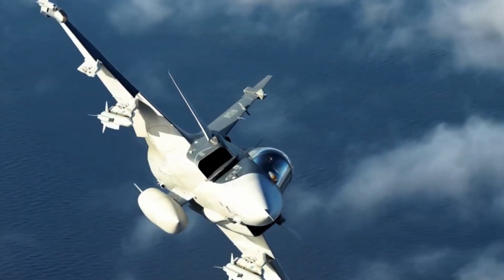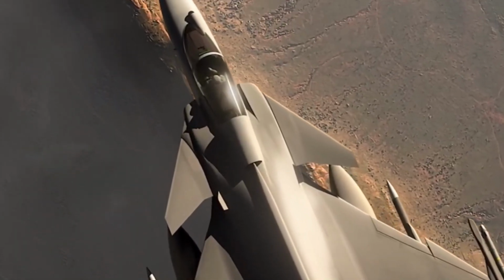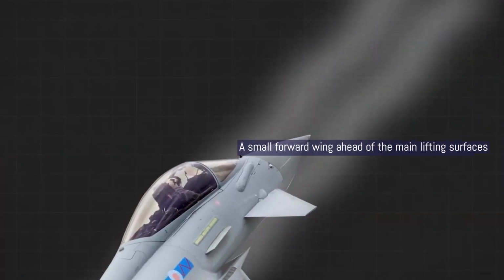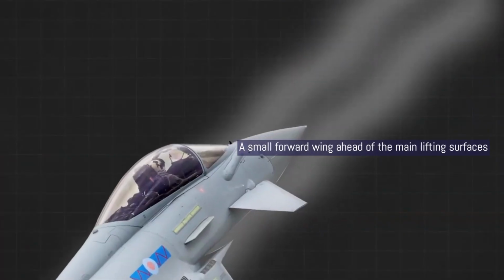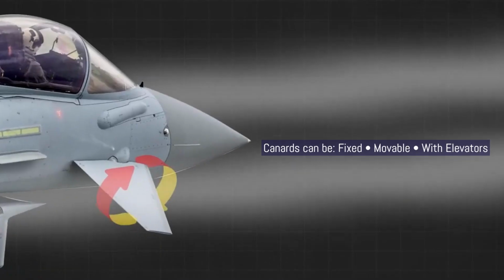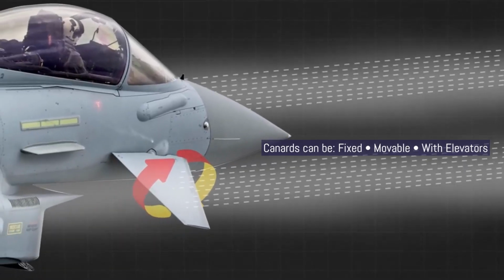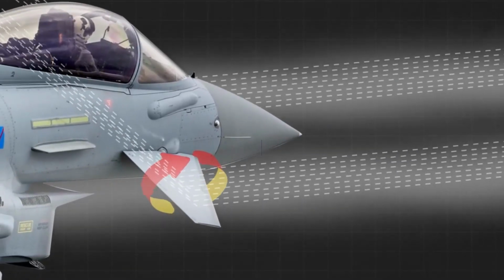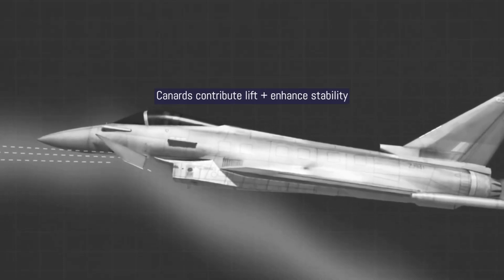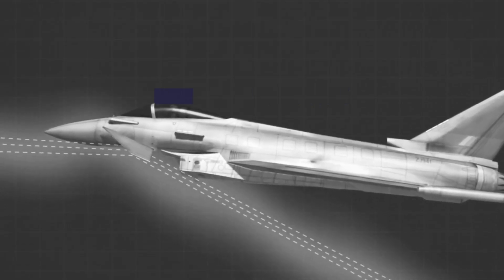Another unique design feature found in certain aircraft is the canard wing. In this configuration, a small wing or horizontal airfoil is placed in front of the main wings, rather than behind them, as in a conventional tailplane layout. The canard itself can take several forms. It may be a fixed surface, a movable wing, or even be fitted with elevators to provide active control. Regardless of the type, its purpose is to contribute to the overall lift of the aircraft while also improving stability and handling in specific flight conditions.